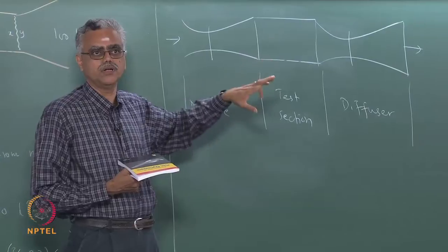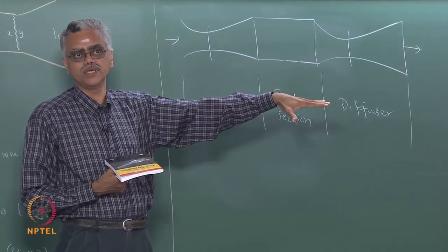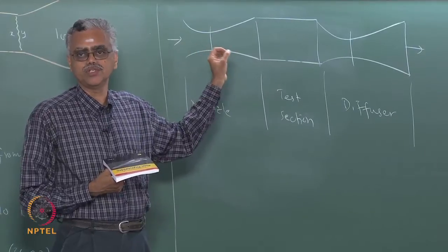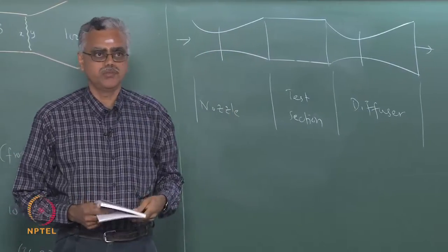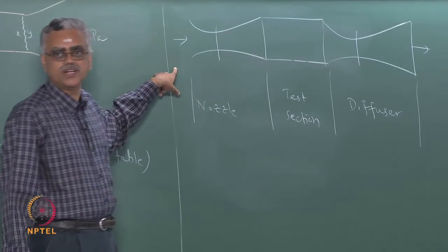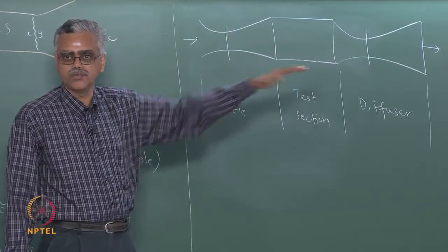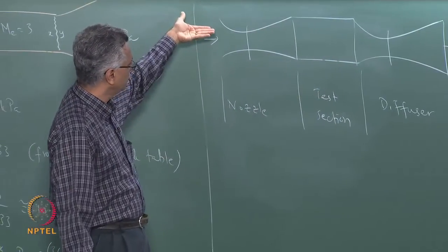In this case we are not lowering the ambient pressure. Yesterday when we talked about this, we were looking at keeping the inlet stagnation pressure constant and then lowering the ambient pressure. Now we are actually running the compressor. So, we are actually increasing the stagnation pressure, keeping the ambient pressure the same, right. So, I increase the stagnation pressure a little bit more.